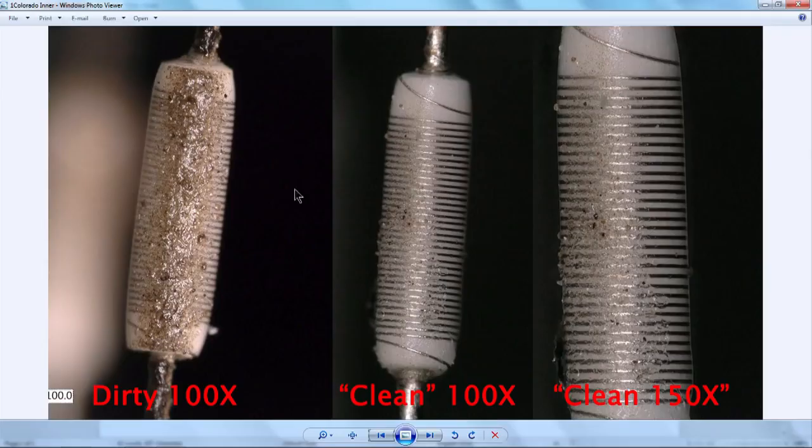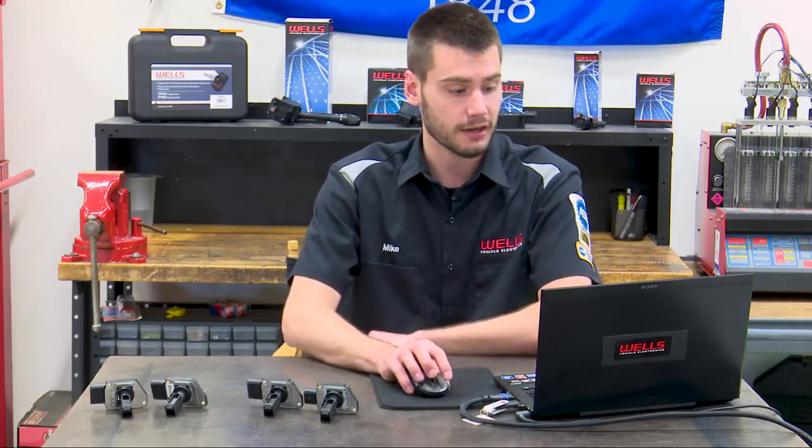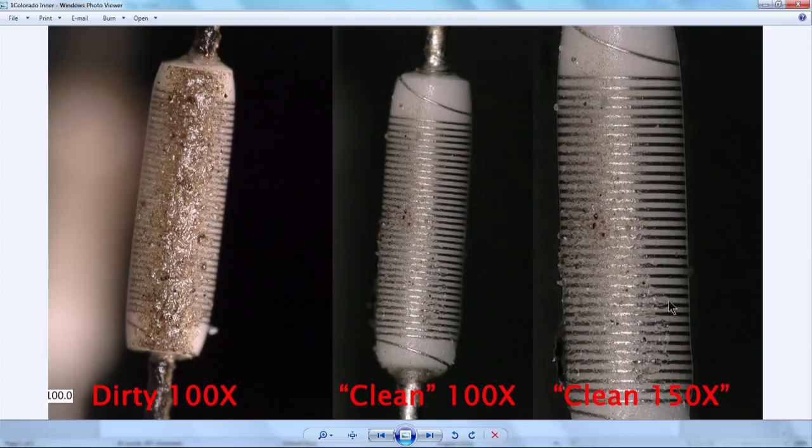Okay, so as you guys can see up on the screen here, we got our sensor just like it looked when we took it out of the Colorado. I showed you guys that picture. It was all caked with dirt and grime and could possibly be tire material. And here's what it looks like at 100 times zoom after being shot with some mass airflow sensor cleaner. And now, I didn't go use half a can of cleaner on this. I sprayed a decent amount, what I thought was enough. I sprayed it down, and you guys can see that it's definitely cleaner. You can see here at 150 times zoom that the sensor has less dirt on it.